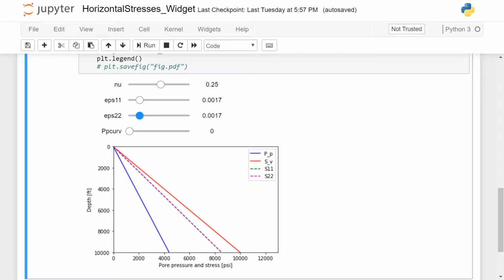All right, there is one more variable there, and that variable illustrates the concept of effective stress. It's very important you remember that all these equations of elasticity are relating effective stresses to strains, not relating total stresses to strains. Because if you do that, you'll get something wrong. You always have to relate strains to effective stresses. Effective stresses are the ones that really make the rock deform or fail. Total stresses will not do that.